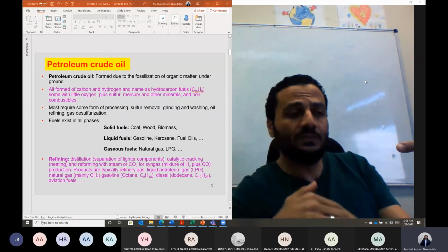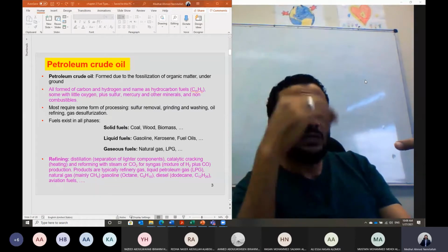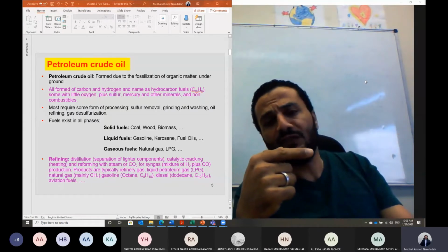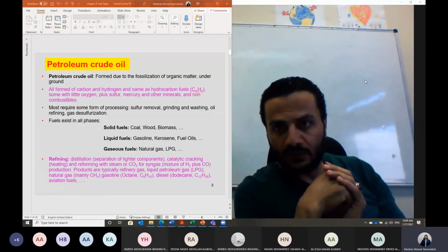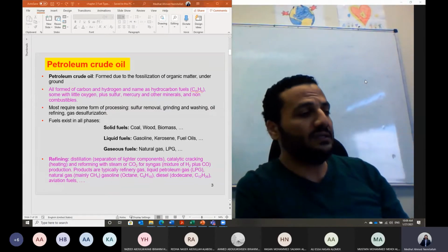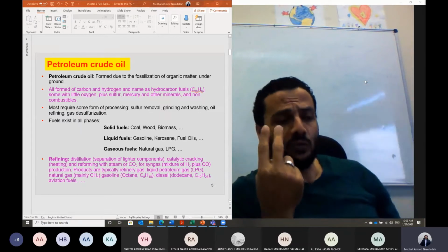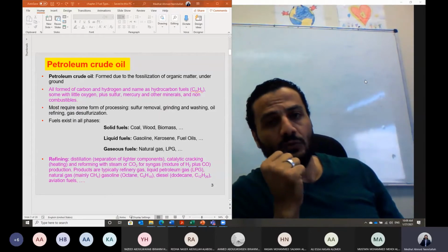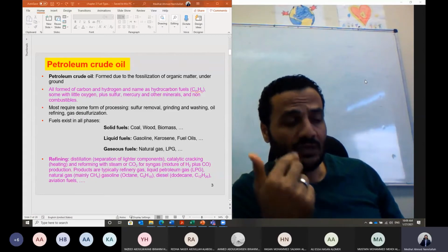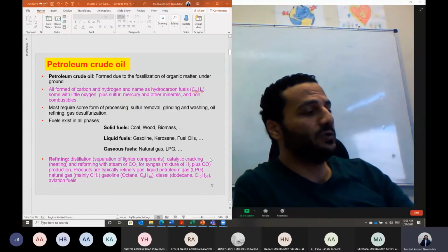While the piston is moving up and down, it just covers and uncovers the intake and the exhaust ports. So while the piston is moving up, we can combine the intake stroke plus the compression stroke in 1 stroke.